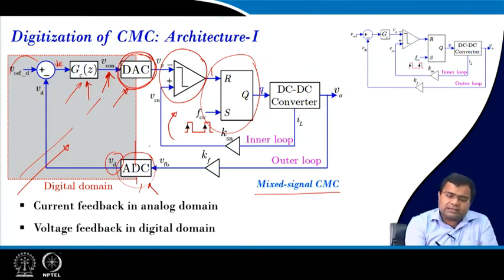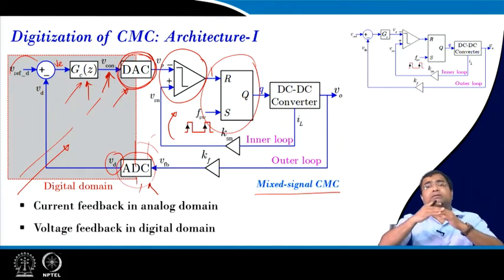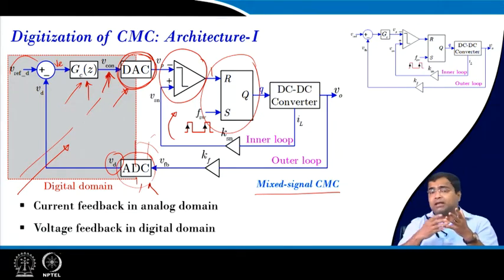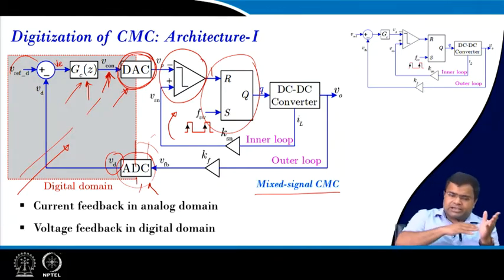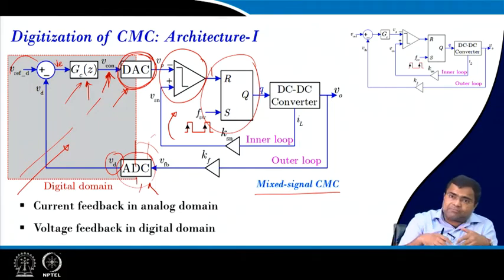But imagine if we take, let us say for example, an analog comparator, and if you look at how voltage loop is deviating within some hysteresis band, then you can quickly ramp up this current by means of some nonlinear algorithm. That means you can increase the current very rapidly, then we can bypass the linear control loop. So all these possibilities are there.